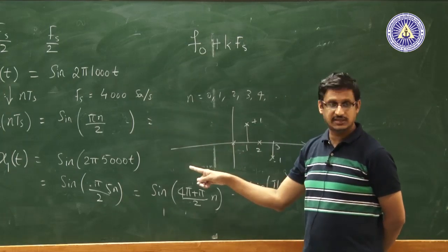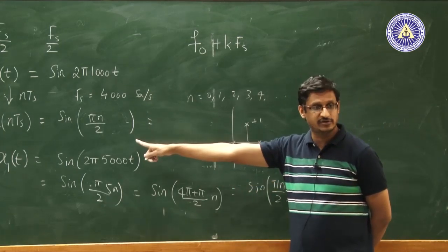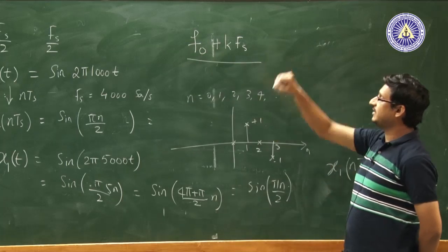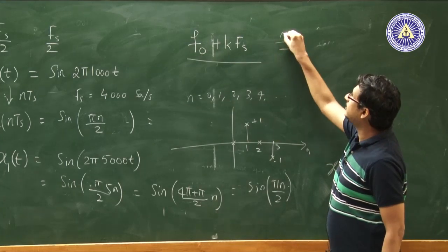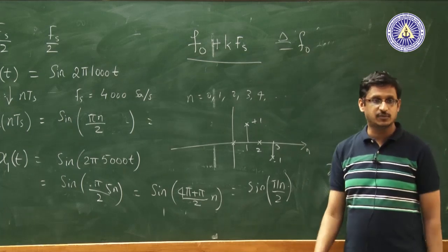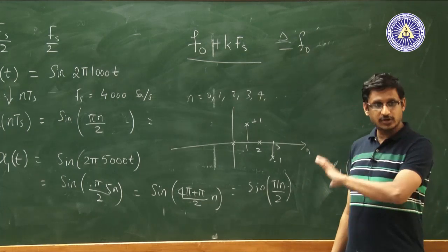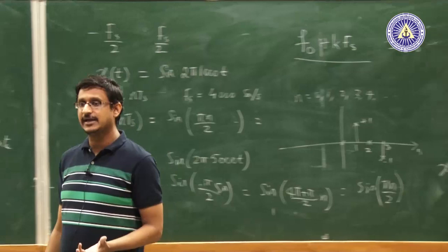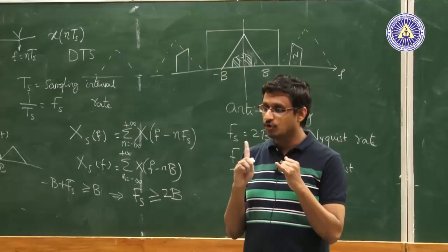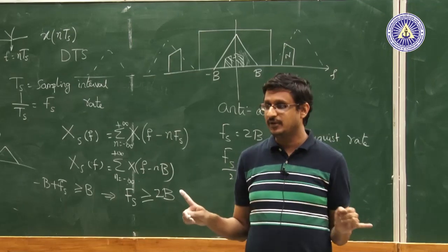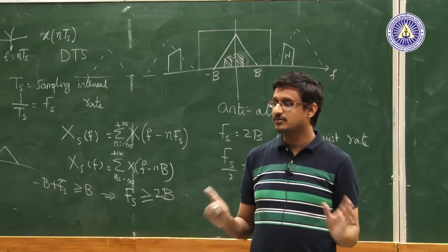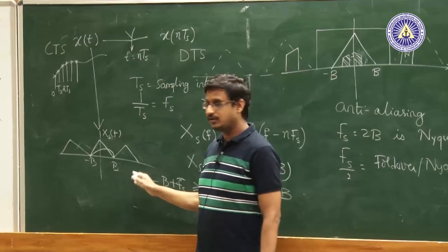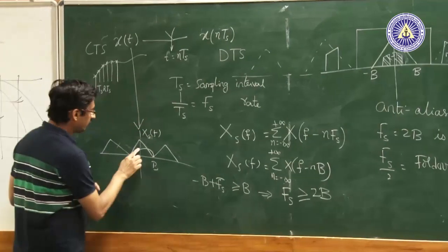Similarly, a 10 kilohertz signal would also go back and look like a 1 kilohertz signal, and so on and so forth. Maybe not 10 kilohertz, we will have to figure that out. Any frequency that is there in this f0 plus kFs will be equivalent to f0 itself of the original frequency, okay. And this problem is what is called as aliasing. So, to determine the spectral components or to determine the spectrum of the discrete time signal, it is very important that you know what is the value of Fs. Without knowing the sampling rate, you cannot avoid the aliasing problem. In fact, that is just a dramatic description of the same thing that is happening over here, right. See, look at this excess of f, right.